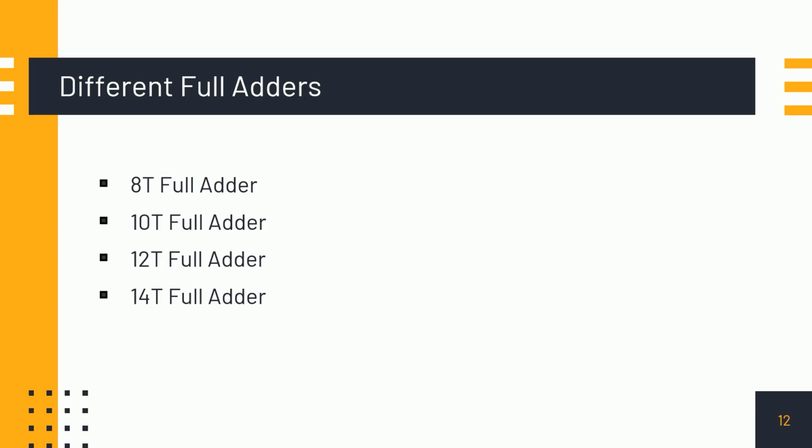However, the adder didn't show improvement in threshold power loss. Hence, the 14T adder would consume significant power as compared to the presented 12T, 10T, and 8T full adders. The 8T full adder doesn't suffer from the threshold power loss problem. Also, the noise margin can be substantially decreased by proper sizing of transistors. In our project, we simulated four types of full adder circuits using Cadence software in 90 nanometer CMOS technology.